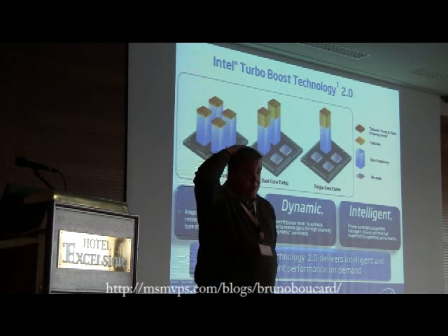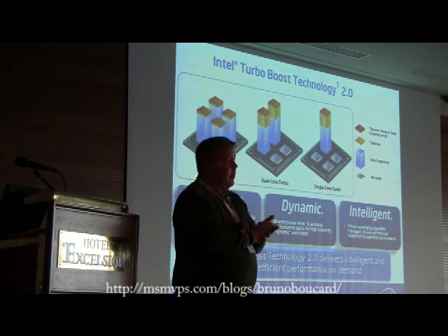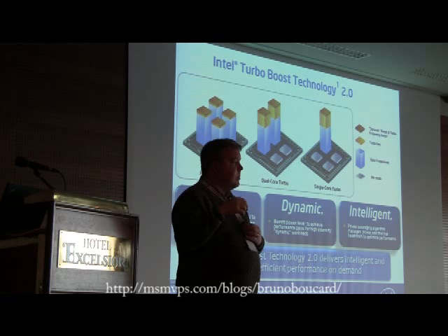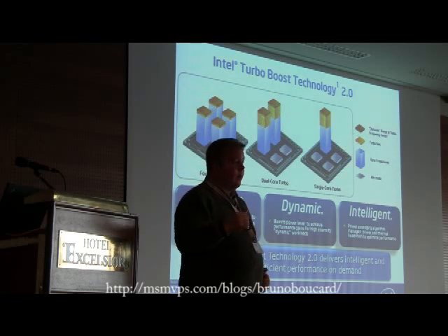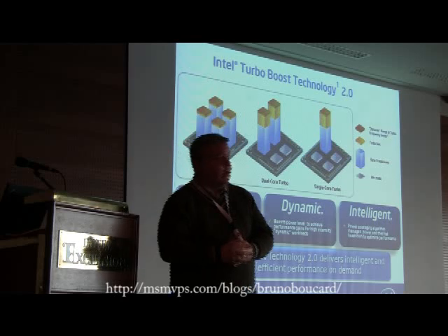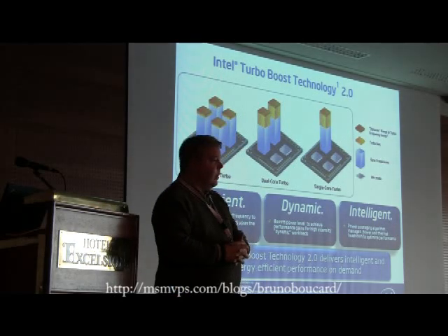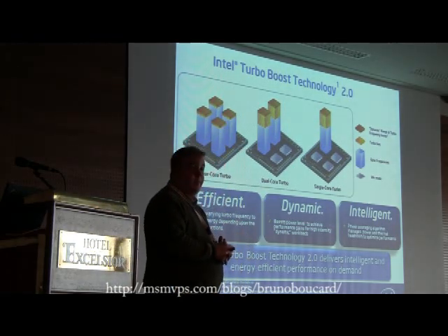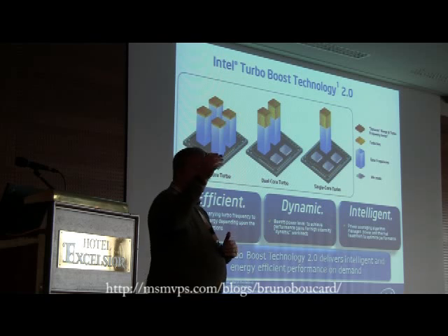So, many years ago, Intel implemented a technology called SpeedStep technology. The idea being that we would clock the frequency of the processor down in order to save power. Well, starting with the last generation of processors, we figured out we could go the other way. If we have thermal headroom and we can shut off one or more of the cores, we can actually boost the frequency up. So why would you want to do that?